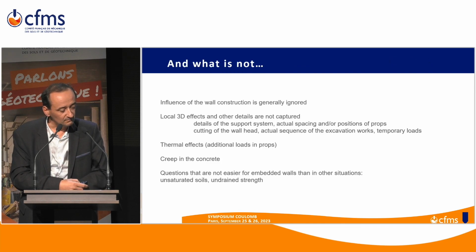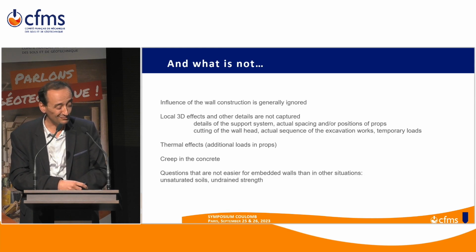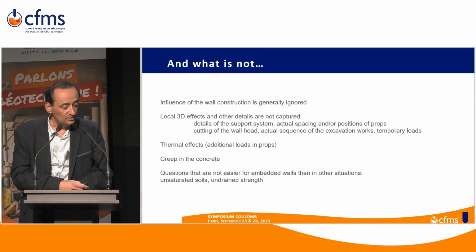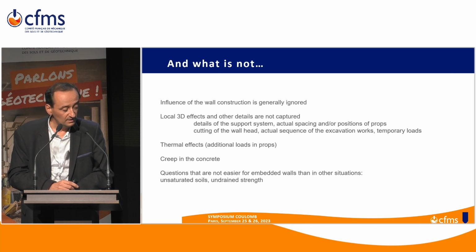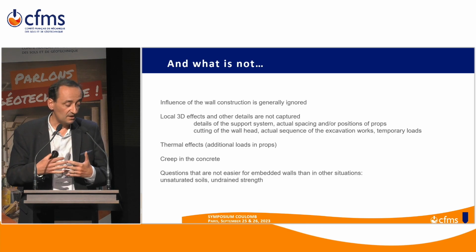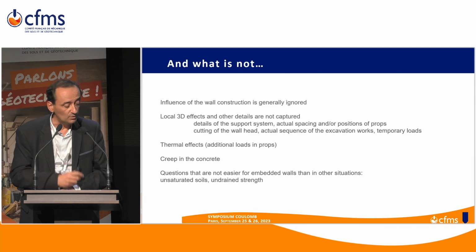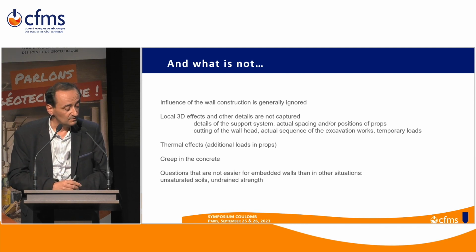Okay, and by contrast, there are some things that are more or less ignored in the models. The details, for instance, the wall construction is generally ignored, which may be of consequence in some cases. Local 3D effects are by nature ignored, and some other details are not really captured. For instance, the actual spacing and the position of the props is necessarily simplified.